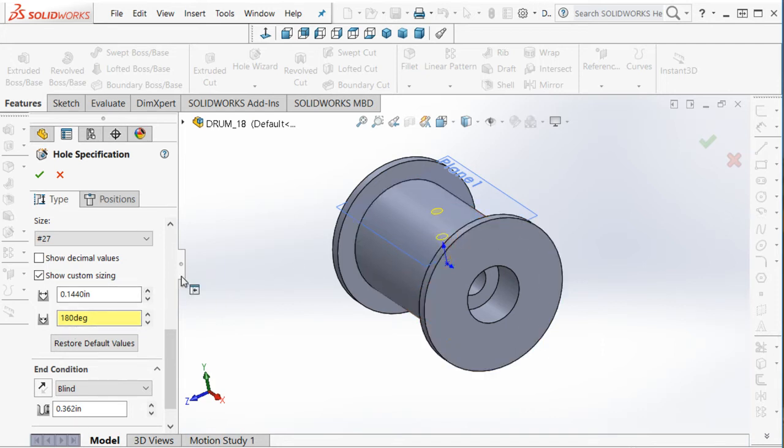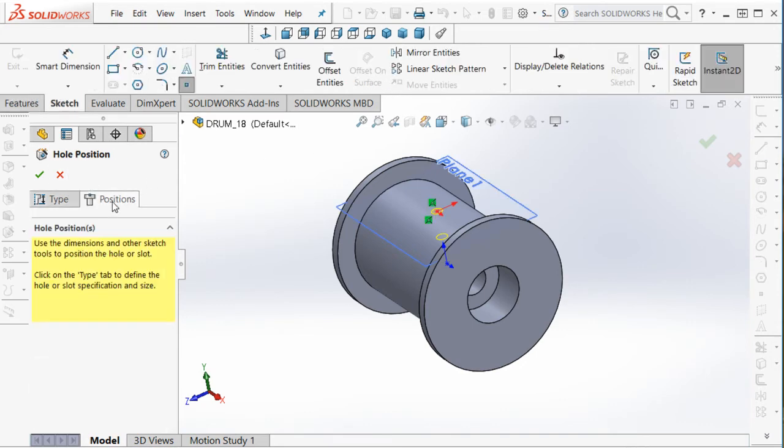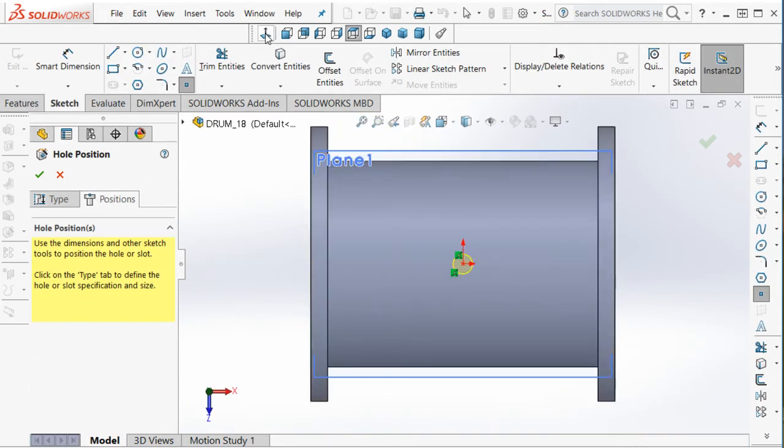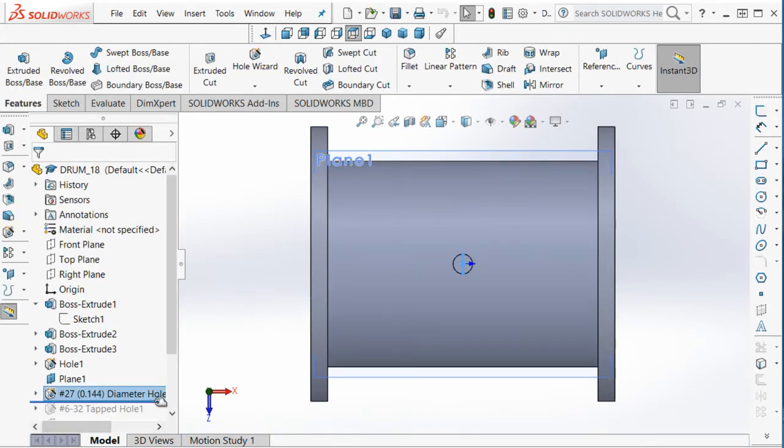All this first hole does is allow me to get to the bottom quarter to 3/8 of an inch of material where I want to put my threaded hole. This is just a clearance hole, really. So I put my position here. Let me go normal to that sketch. And this is where it came in handy to have the origin at the center. It allows me to put the set screw also at the center without having any additional constraints on this sketch. So that's my second hole.